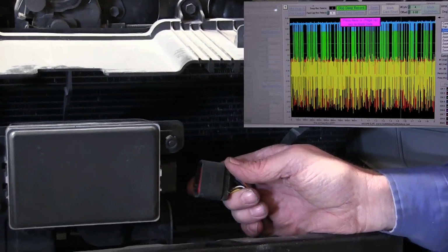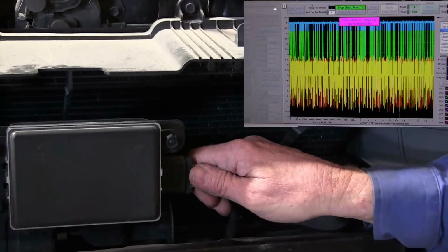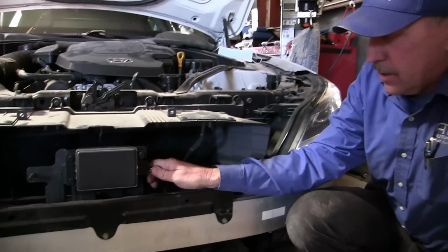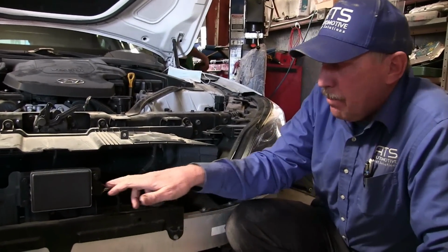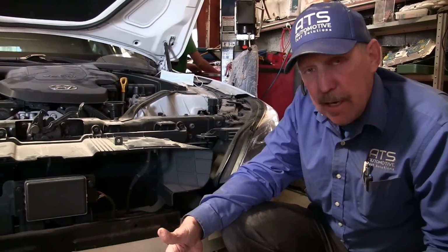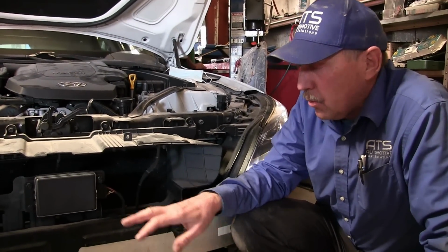Okay, so the scope still is pulled down, so that is not my problem. Always reconnect what you've unplugged so we don't have another problem. You can actually create problems by leaving the stuff unterminated, and you can start a bus ringing when you get enough of these unplugged. So we only do one at a time, and we're going to replug it in.